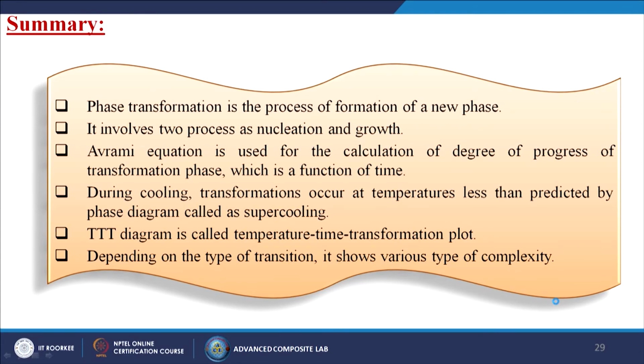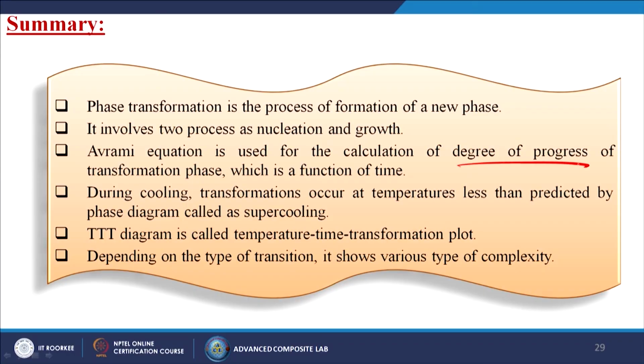So, now we have reached the last slide of this particular lecture, and we have to summarize the whole lecture. In this lecture we have discussed phase transformations, which is the process of formation of new phases and generally involves two processes: one is nucleation, another one is growth. The Avrami equation is used here for calculating the degree of progress of transformation, which is a function of time. During cooling, transformations occur at a temperature less than that predicted by the phase diagram, called supercooling.